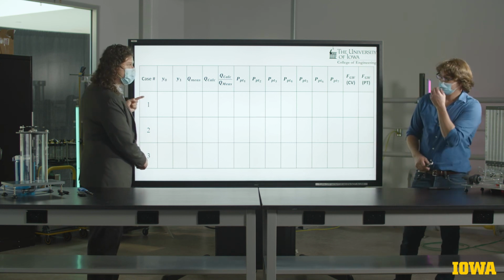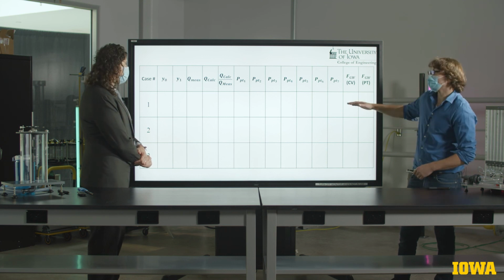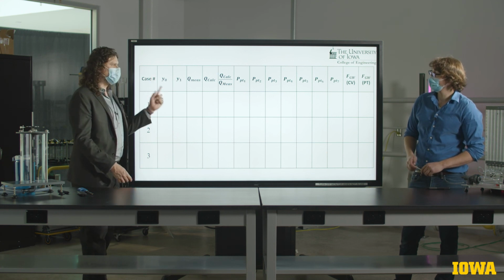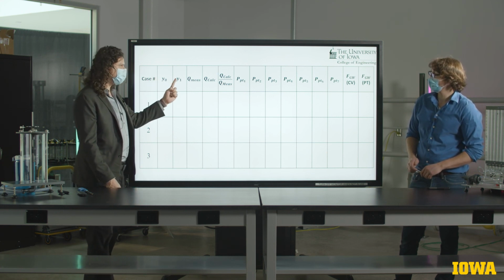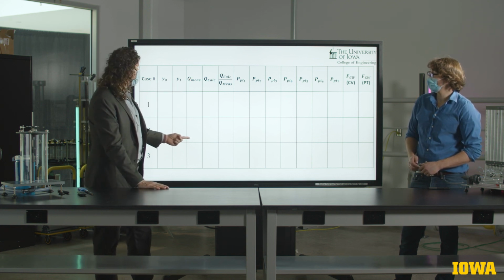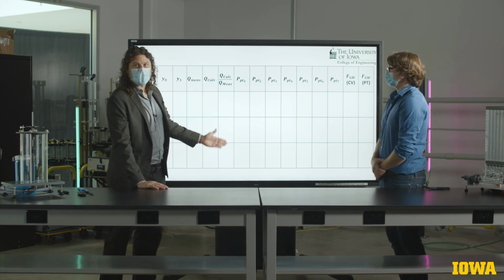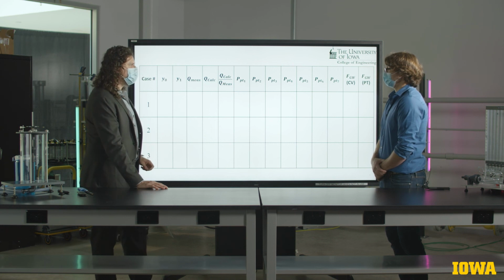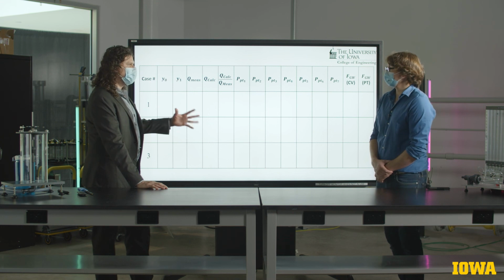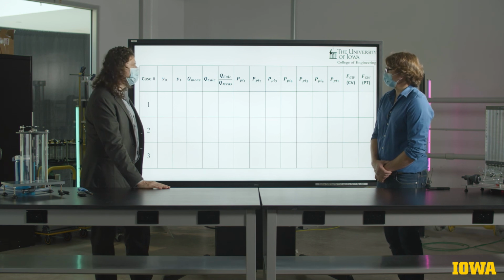So here we did 3 measurements of the elevations. We repeated the exercise 3 times at different flow rates. And for each one of those, we measure the variable y1, the upstream depth, the downstream depth. We had a flow that was measured by our mag flow meter. We have our calculated, and on this table we have a ratio of these 2 measurements, because that's going to give us a sense of how good our assumptions, the assumptions that we made on our conservation equations hold.